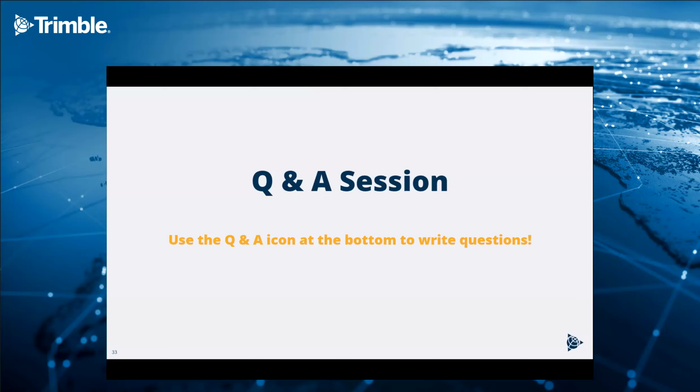The first answer is, we can process data from a fixed wing or a copter scenario, it doesn't matter. As long as the RINEX file is kinematic, we are able to process. The second point is the combination of GNSS and inertial data, and that is not supported here.